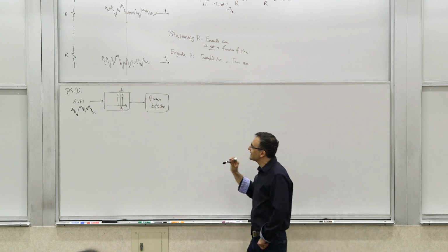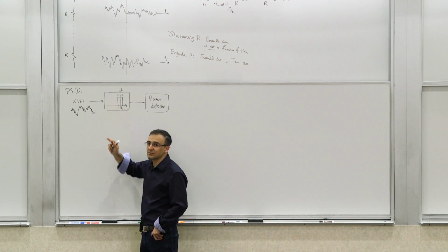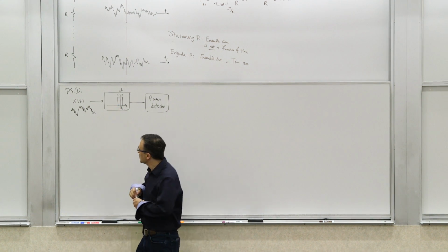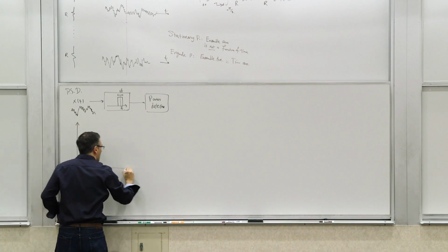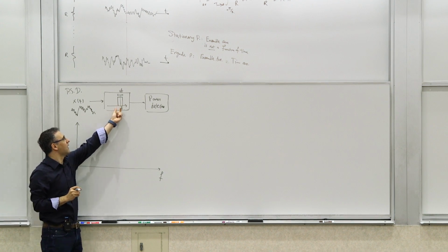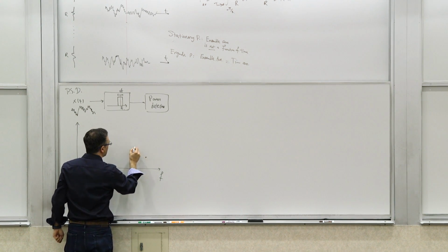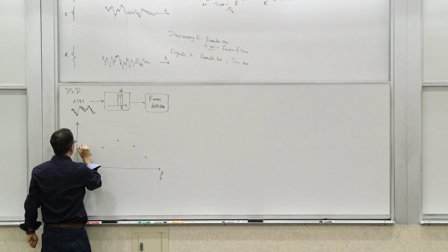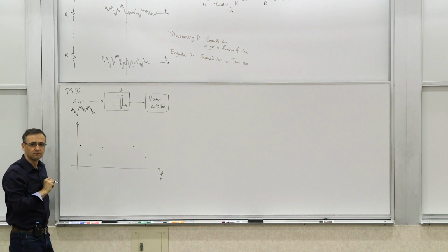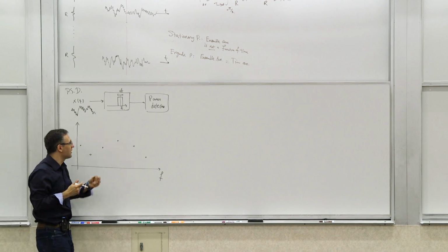Now, if you dump it into a power detector and then start moving this filter to different frequencies and doing different measurements, what would you see? You will get a plot versus frequency. If you start with a large bandwidth, you get a number here, a number here, a number there, versus frequency. You get data points. Now, if you want to get a finer and finer resolution, what do you need to do? Shrink delta f. Shrink the bandwidth.